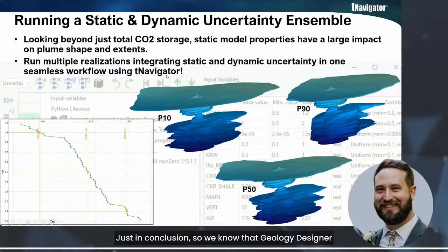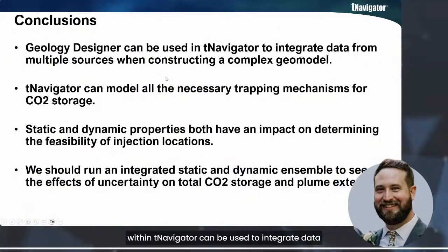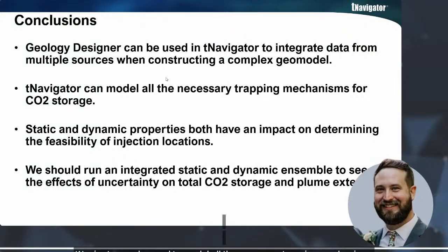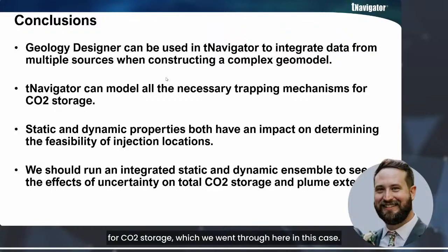In conclusion, we know that Geology Designer within T-Navigator can be used to integrate data from multiple sources when constructing a complex geomodel. We've done that. We've brought together our well data, our seismic data, and we've used attributes from seismic to help distribute the well data where we only have 2 wells. T-Navigator can be used to model all the necessary trapping mechanisms for CO2 storage, which we went through in this case. And we know that static and dynamic properties both have an impact on determining the feasibility of injection locations. So not just the volume of storage, but where is that CO2 actually going to go?